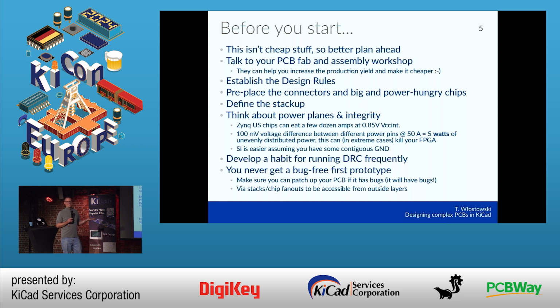This is not a $10 PCB that, well, if you reverse the layers or made a short circuit on the internal layers, you would throw away, right? It requires a bit of planning ahead. So first, go to your PCB fab and whoever will be assembling that PCB. Ask them about their internal design rules.